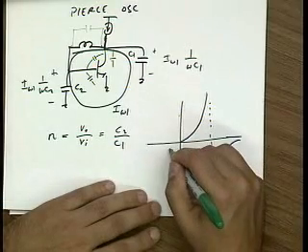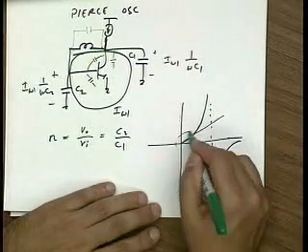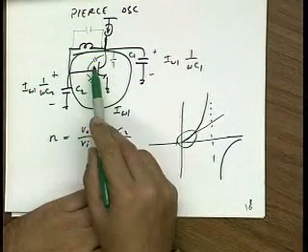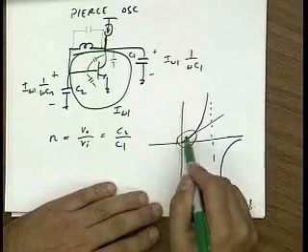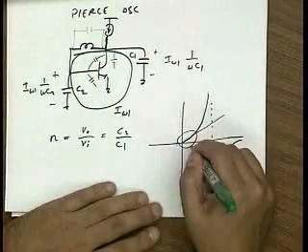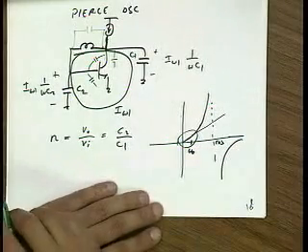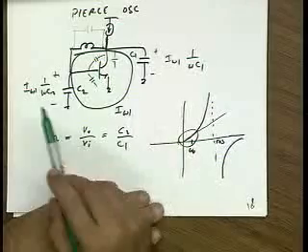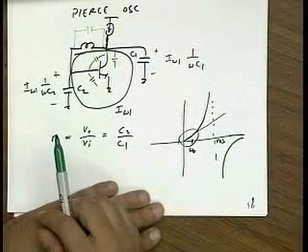If I'm really below resonance, then this looks like a straight line. It looks almost like a perfect inductor. So as long as C mu is much smaller, right, so the resonant frequency is much higher than the frequency I'm operating at. So let's say this is omega naught, and this is the resonance of C mu plus L. If I'm operating over here, the effects of C mu are pretty negligible. Okay.